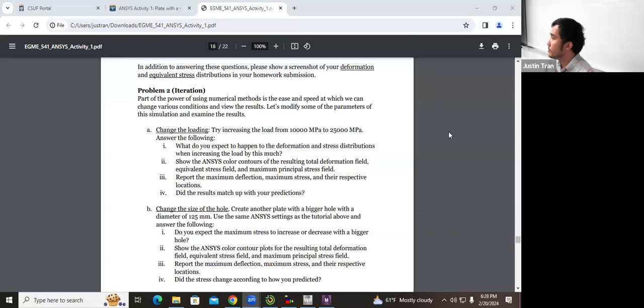If hypothetically you've got ANSYS 21 and SolidWorks 24, can we take the model from SolidWorks and put that into ANSYS? Yes. ANSYS actually doesn't read SolidWorks files directly, so you would have to convert your SolidWorks file. Usually I like a Parasolid file, file format x_t. From SolidWorks, you would click Save As and then save as an x_t file. Then you can upload that into ANSYS. That file format is irrespective of the different versions.